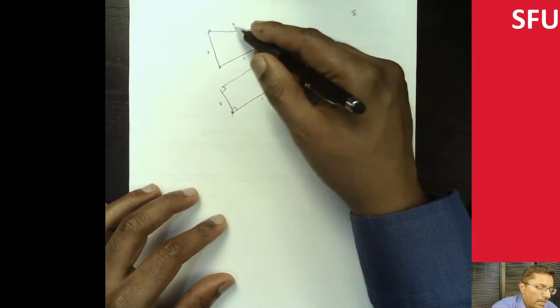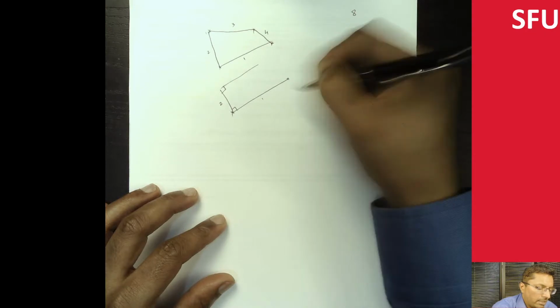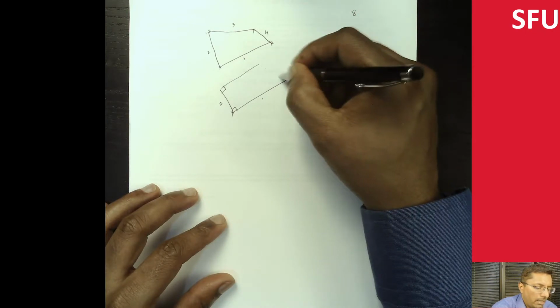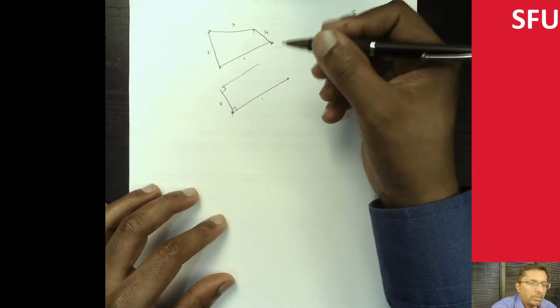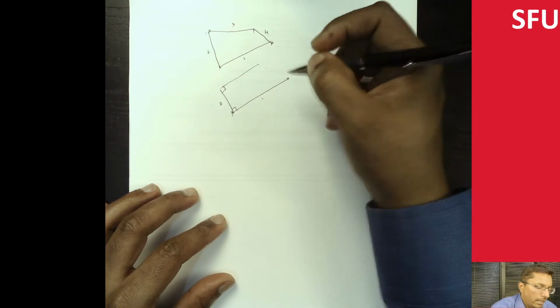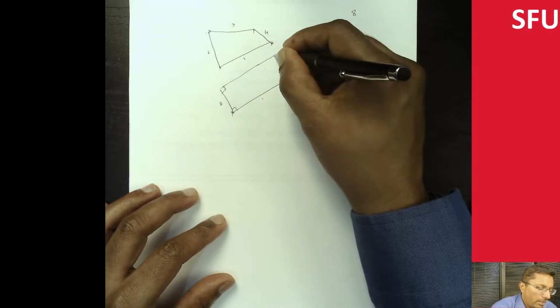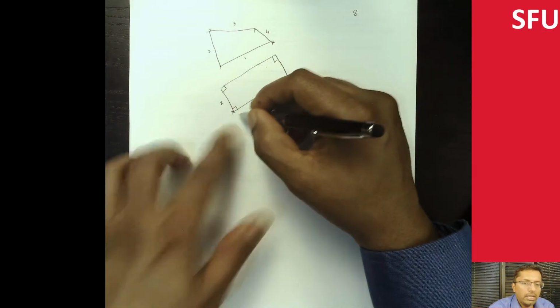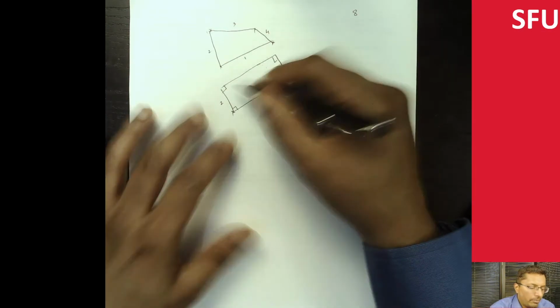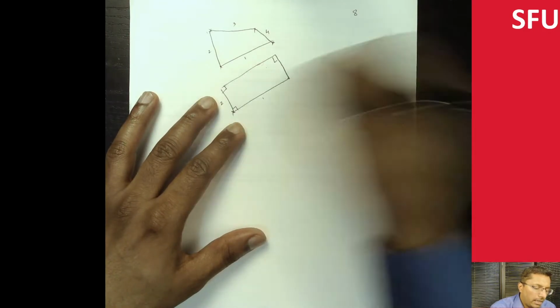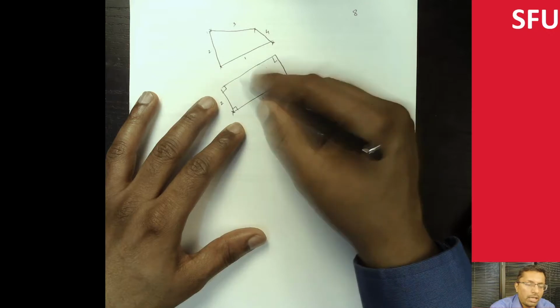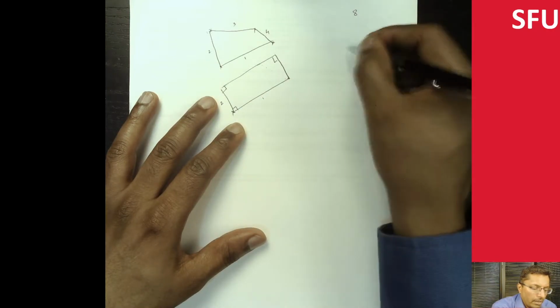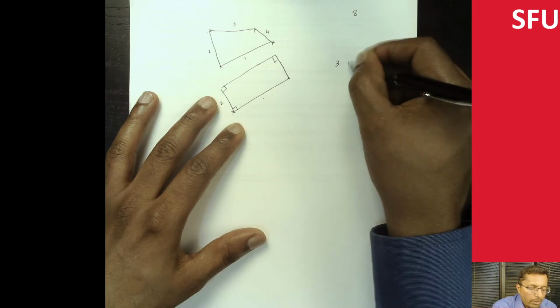And then once I do that, I have the other line. So I basically have this as the end point. So this is my other fourth line. So I want to make this perpendicular as well. So what I would do is essentially just change it. And then if I make this perpendicular, I'm going to end up with a shape like this. So this basically means I have reduced the number of constraints. So I define 8 constraints for the different points, and then I have 3 constraints to be perpendicular.